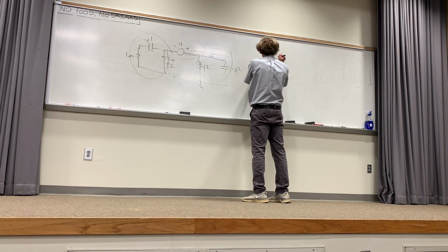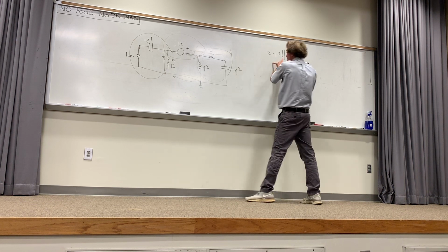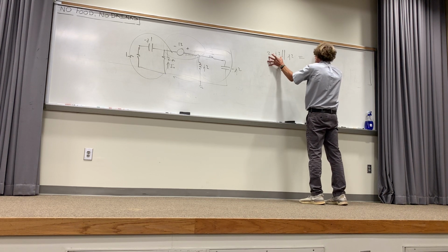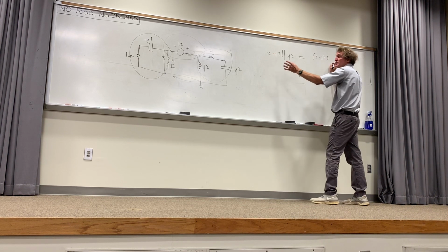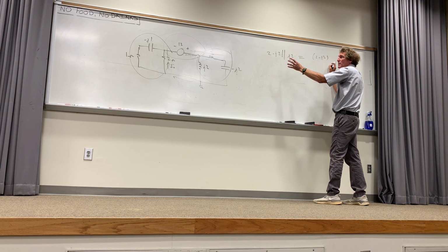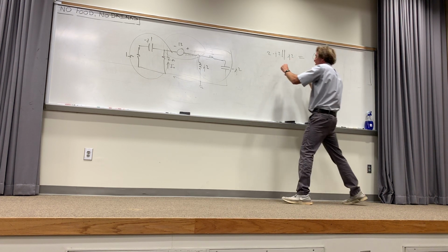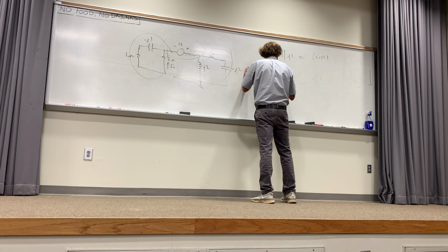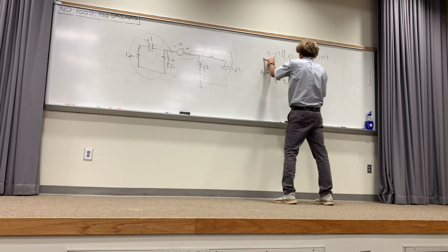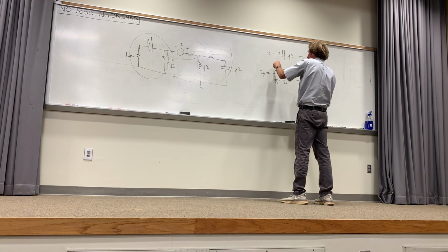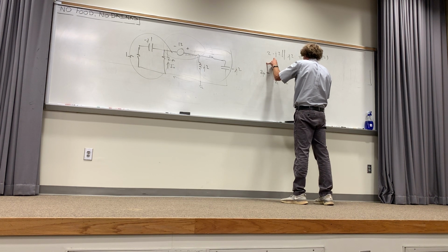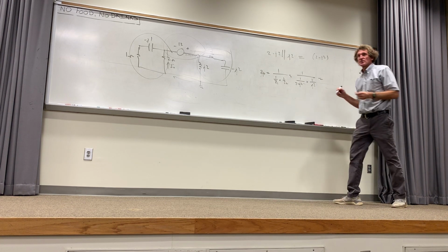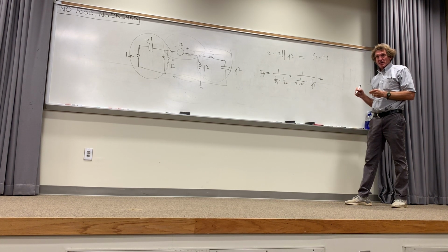So I have 2 minus J2 in parallel with J2. That's the symbol for parallel. Now, that's equal to, you can take that impedance, 2 minus J2. Your calculators will do this very quickly, by the way. If you want two parallel values, technically Z parallel would be equal to 1 over Z1 plus 1 over Z2. Watch this. Now it's equal to 1 over Z1, which is 2 minus J2, plus 1 over Z2, which is 1 over J2. Your calculators can do this in a heartbeat, right? And you can get a single value.